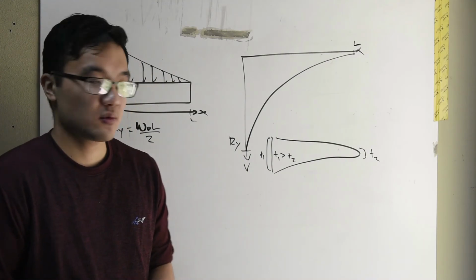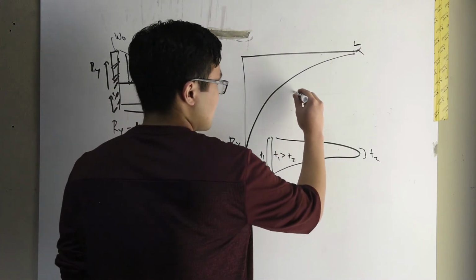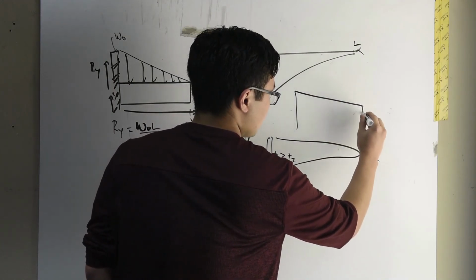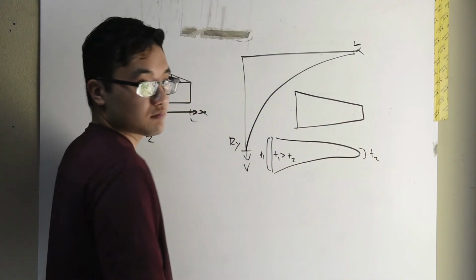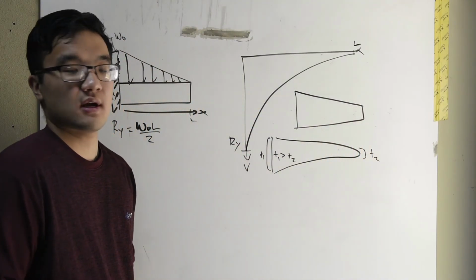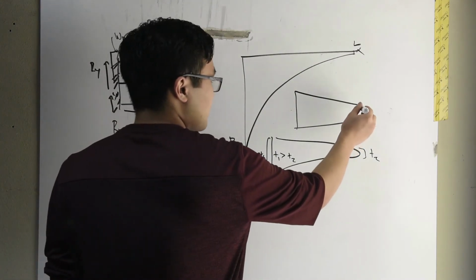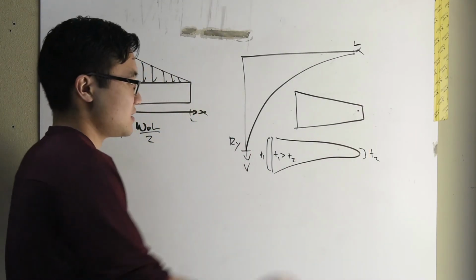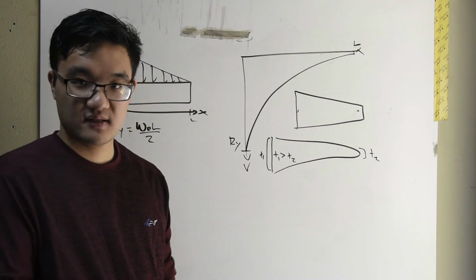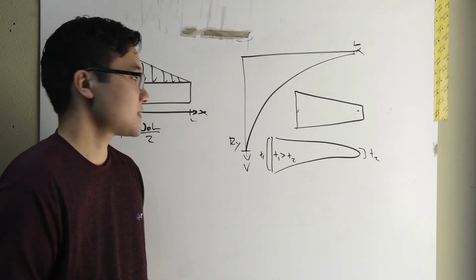Again, let's say we taper a wing, right? Let's say from the top down the wing looks like this. That's fine given our loading criteria because we don't need this point to support as much, but this does. That's why it's thicker. That's why taper works.